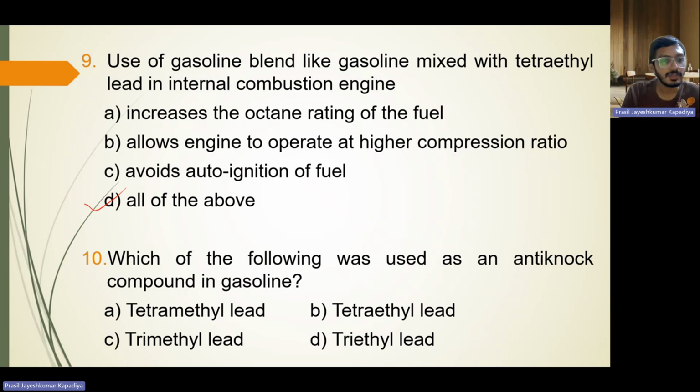And what happens if the compression ratio is higher? It will result in higher temperature of the charge, and because of that temperature, this knocking will increase. Another factor is inlet air temperature. So what is the effect of inlet air temperature? It is the same effect as the compression ratio. The higher the inlet temperature, the higher the possibility of increasing the knocking.